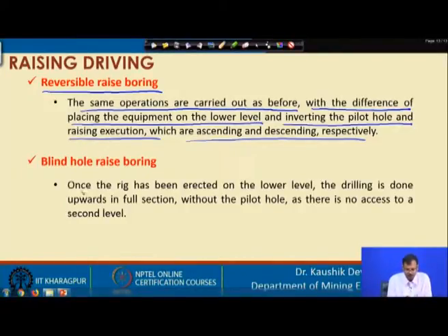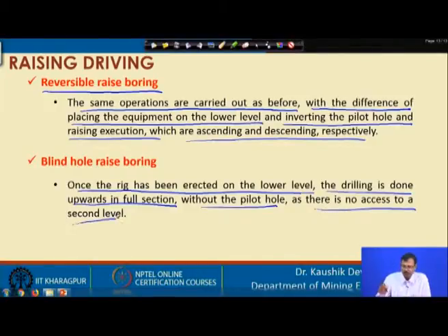Blind hole raise boring: once the rig has been erected on the lower level and the drilling is done upward in full section without a pilot hole, it is called blind raising. So, that means here the upper level is this, lower level is this, and you start carrying out drilling from the lower level to upper level with a drilling head like this, which drills the material and goes in the upward direction.